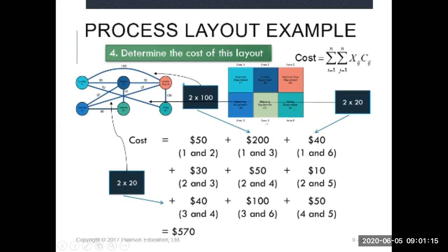Of course we can, because we can see here the cost is quite high, 100, but they have to move 2 times. So this is what we want to reduce, the material handling cost. Assembly and machine shop should be put side by side, because the handling cost between these two departments is quite high. That's why we have to move assembly near to the machine shop.